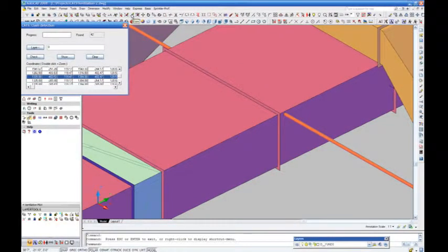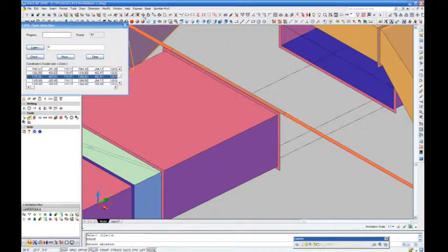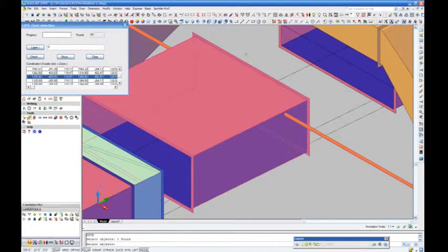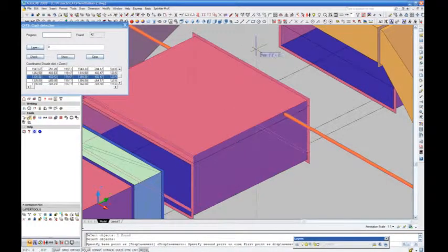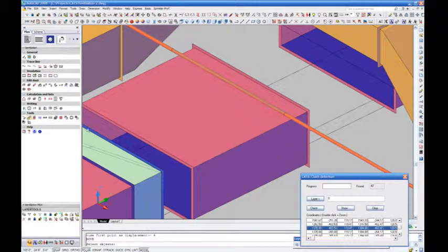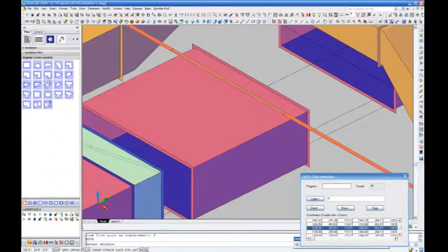We will delete one duct section. The correction will be made by moving the supply duct forward 12 inches and down 4 inches. We reconnect the section through the offset command.